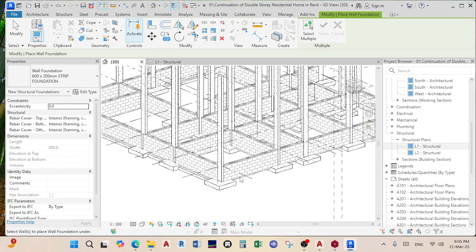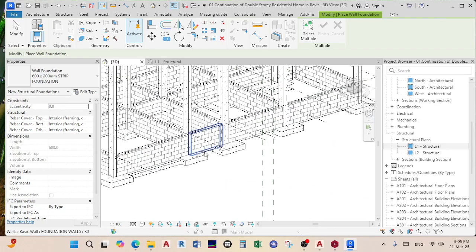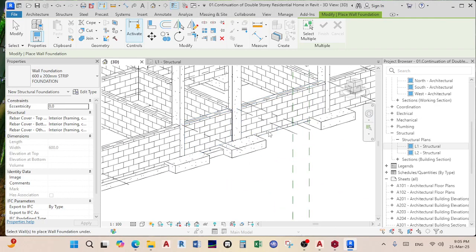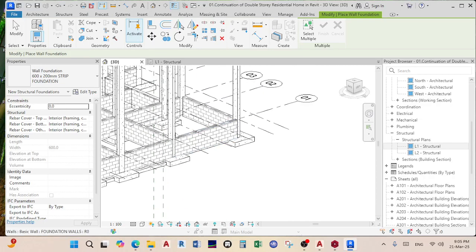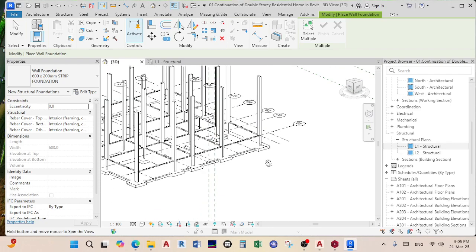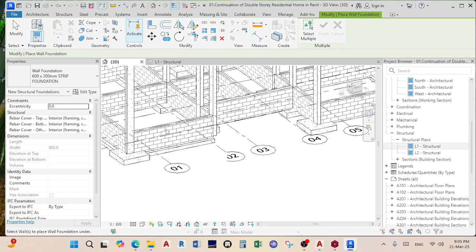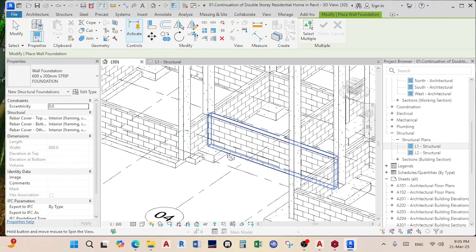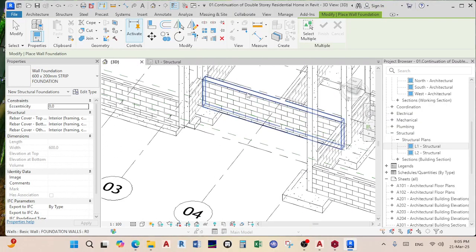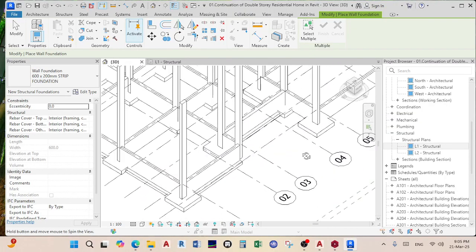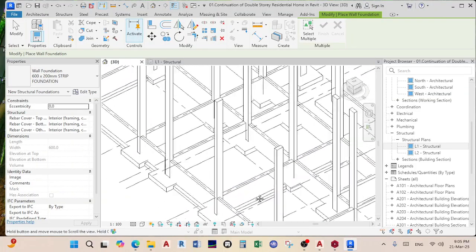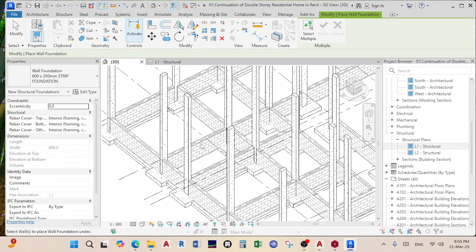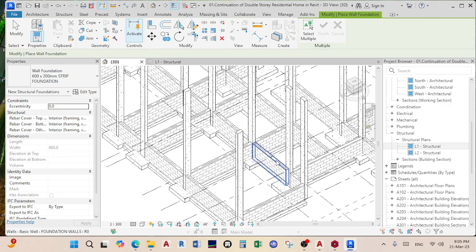and then you can try to select these walls like that, and they'll be adding the footing or the strip foundation like that. And then you can do this in 3D, or you can do it in 2D like that. Select it, it adds the little footing, and then when you go into your 2D, you see whether you're missing certain walls or not. Like that, like that.